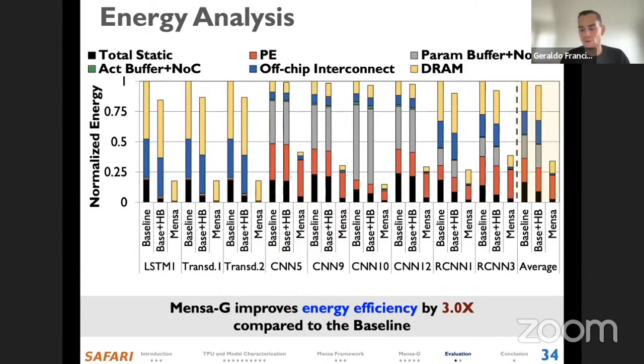Other than the near-data aspect, where we are leveraging high bandwidth DRAM when you go inside memory. But the organization is pretty much the same. You have a systolic array that's fetching data from memory and executing back operations, right? So I believe that probably even the baseline Edge TPU accelerator could benefit from such specialized data flows.